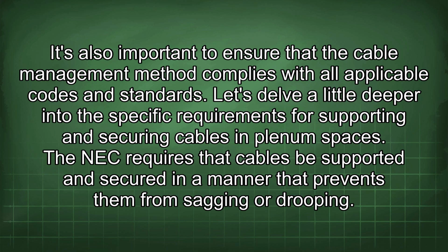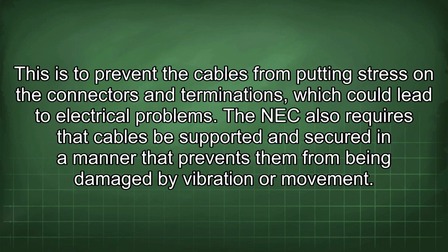Let's delve a little deeper into the specific requirements for supporting and securing cables in plenum spaces. The NEC requires that cables be supported and secured in a manner that prevents them from sagging or drooping. This is to prevent the cables from putting stress on the connectors and terminations, which could lead to electrical problems.